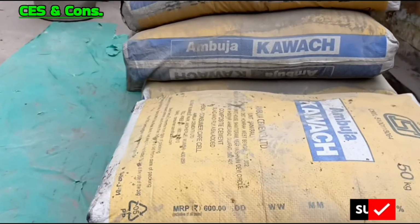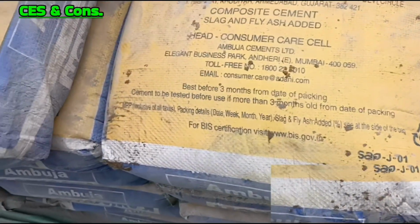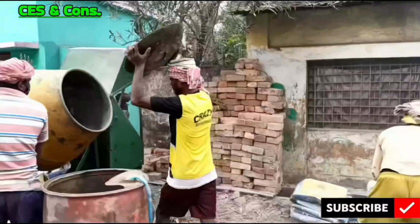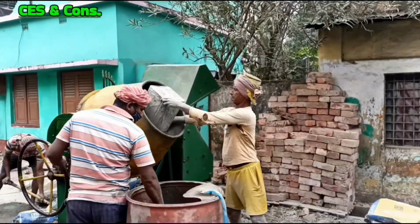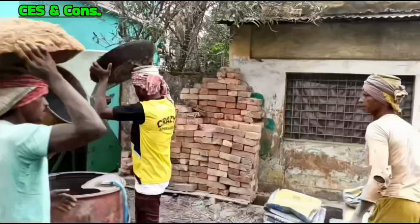Friends, these were the specifications of all the materials required in the work. Now moving to the construction. Here concrete is being prepared using a mechanical mixer instead of hand mixing. It ensures uniformity, speed and quality control, especially for medium to large scale works.